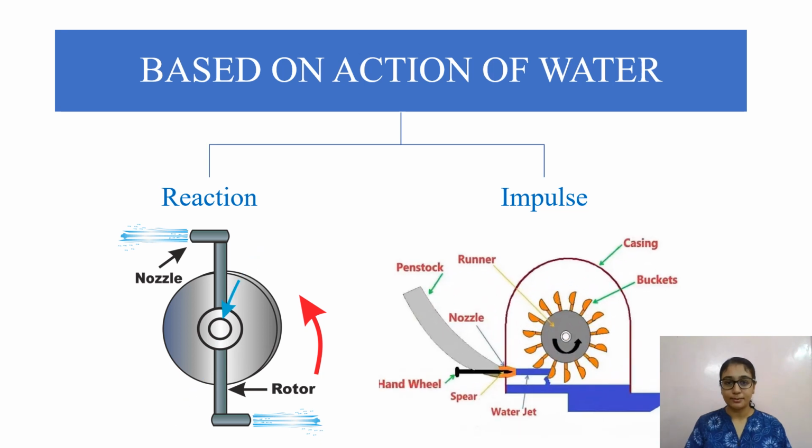Second is the impulse turbine. Impulse turbines change the velocity of a water jet. The jet pushes on the turbine's curved blades, which changes the direction of the flow. The resulting change in momentum or the impulse causes a force on the turbine blades. Since the turbine is spinning, the force acts through a distance, and the diverted water flow is left with diminished energy. An impulse turbine is one in which the pressure of fluid flowing over the rotor blades is constant and the work output is due to the change in kinetic energy of the fluid.